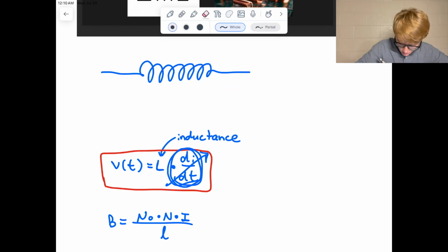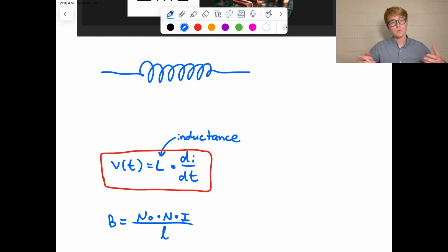So there's that. Now, as we get higher and higher frequencies, di/dt takes on a larger and larger value, so my V(t) gets larger and larger. So now we see a larger and larger voltage drop across the length of my inductor. So what does that mean? That means that my inductor is looking like a larger and larger resistor. And if I have a resistor with infinite resistance, then that's the same as an open circuit, right? So if I have a super large resistance, that's basically an open circuit, which is exactly what we said before.